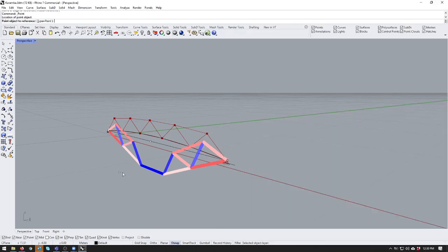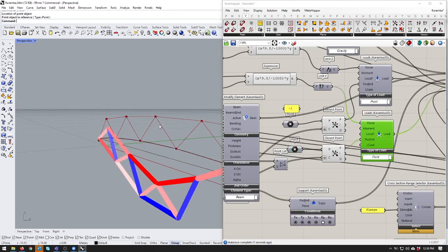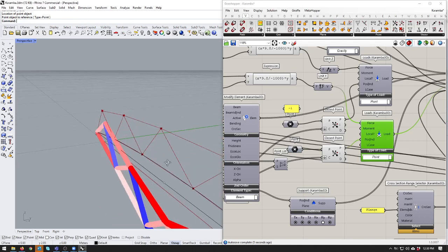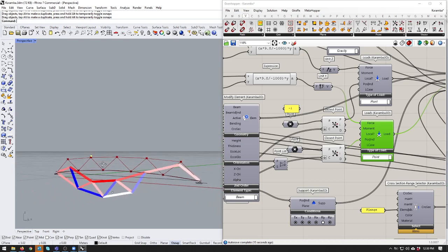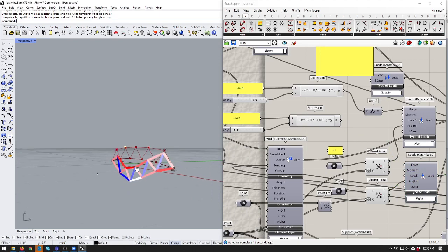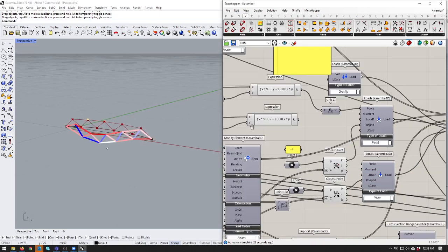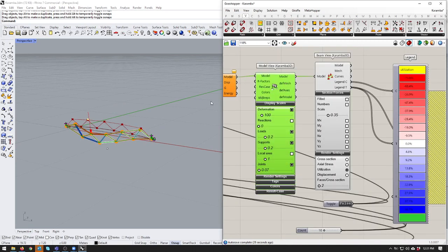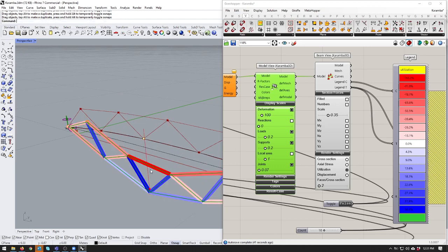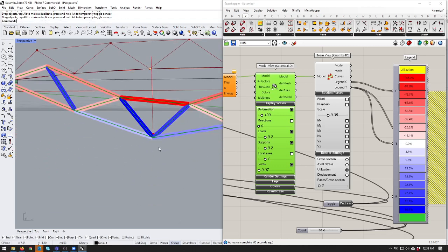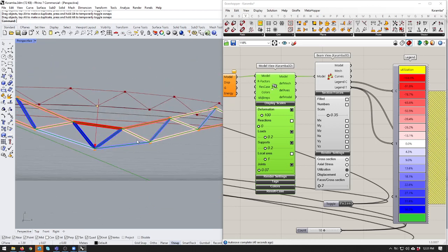What's the point that you've got the load being put on? The point that the load is on will be this one. Okay. Or actually, it's maybe one of these two. If I lift that up and move it along, it'll move that to where it needs to go. I'm just going to turn off that extra load. You can see the forces if you turn your model view on. The force will show up. See that red line? That's showing you which node that particular force is being applied to. So if I move that along or down, see now that force is on that bottom node there. Yep. Okay.